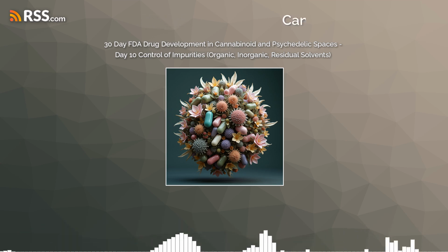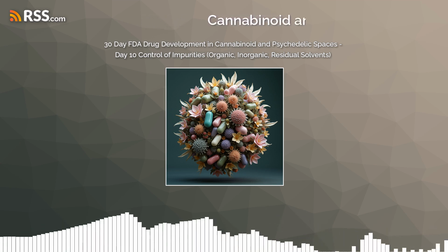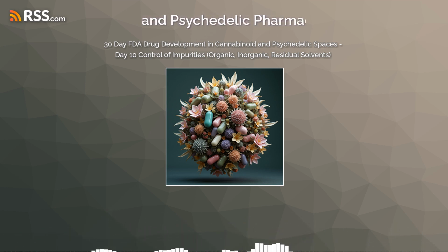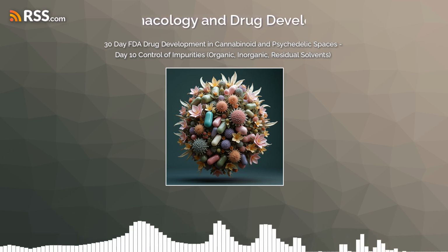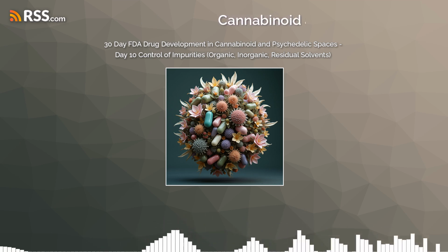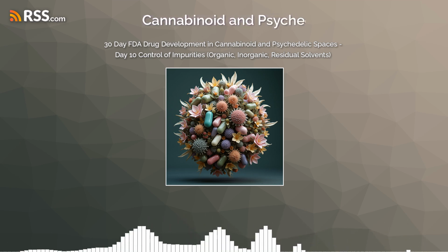The purge factor for that step would be 100. So the higher the purge factor, the better that purification step is working. It's kind of like a measure of efficiency. Exactly. And these calculations are important because they let us know whether the step is actually doing what it's supposed to be doing. Ultimately, it all ties back to making sure that the final product is safe for patients.